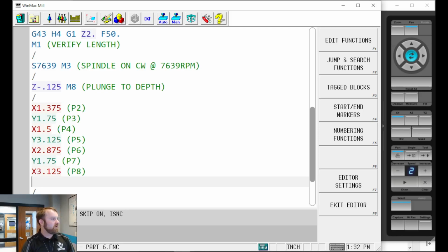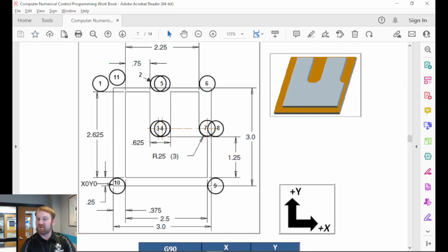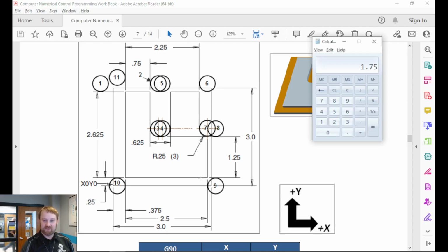Alex Shetterly, can you get me to 0.9? Y 0. 0.9. And I like 0.9 because that's one that really is tough and I want to visually look at it and be like, oh yeah. But you got to do the math. It's pretty simple. This edge is at 0.25 minus the tool radius 0.25, 0. Okay, simple stuff there.